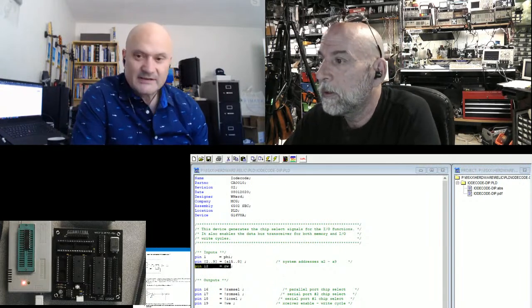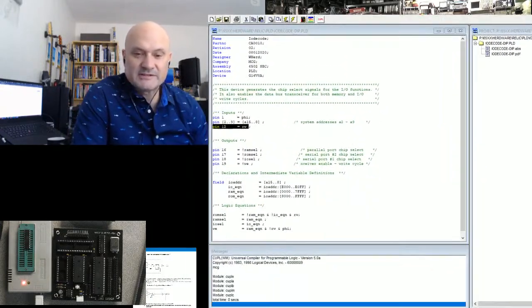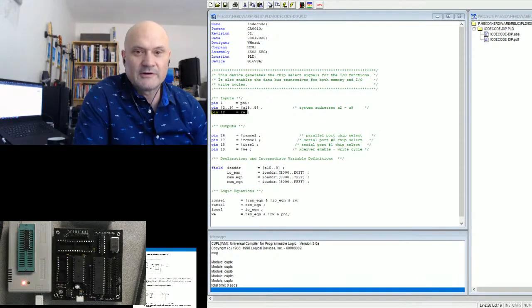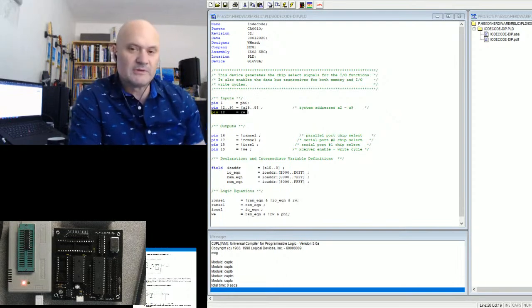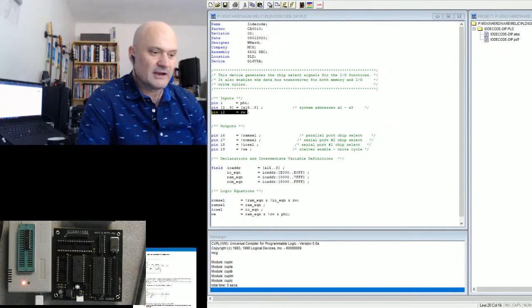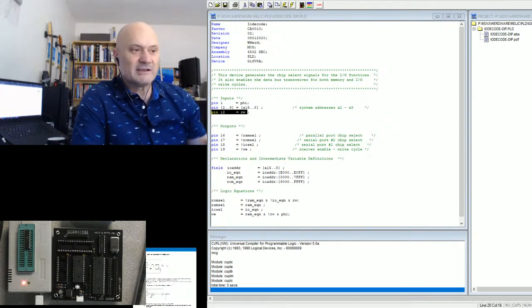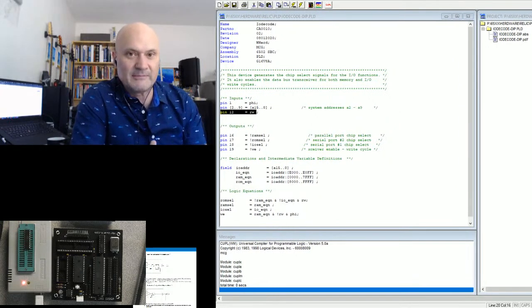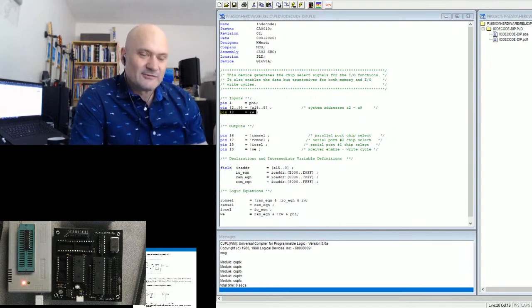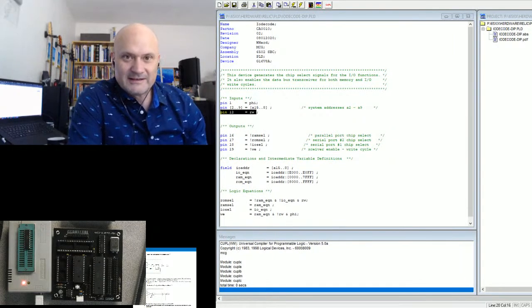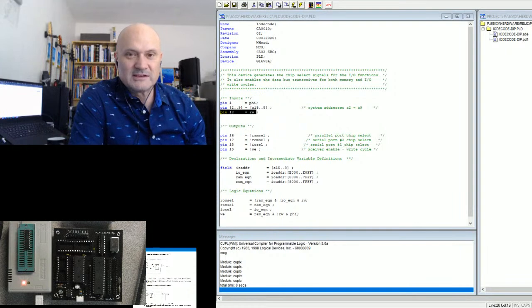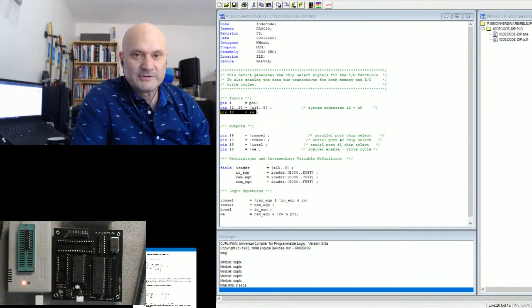You could almost think of strobes in memory devices as the clocks, even though they're asynchronous. And we call them strobes because there's not a master clock that it all has to be synchronized to. So that's the difference between synchronous RAM and asynchronous RAM. But the strobes are still kind of a clock, and it's good to think of them that way, because then you're remembering about those setup and hold times.